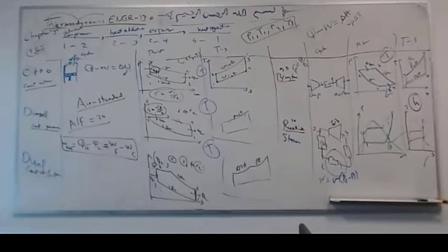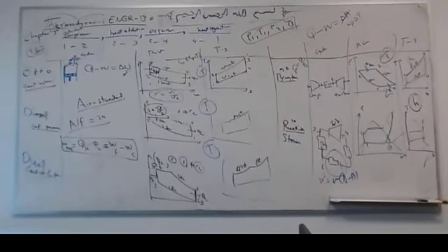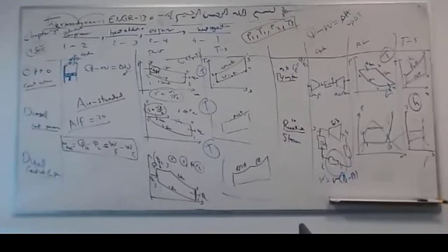Okay, guys. Any questions? Yeah, just had a quick question. You said CP minus CV equals R, right? Yes, of course. Go back to chapter 3 when we discussed the ideal gas law. We said CP over CV is k, the specific heat ratio. CP minus CV is R, the gas constant. That's the definition of R. If you don't remember, go back to chapter 3, I think lecture number 3 also. Okay, ideal gas law.